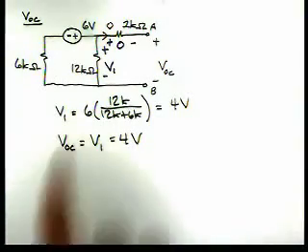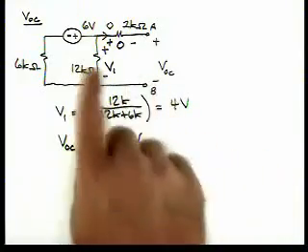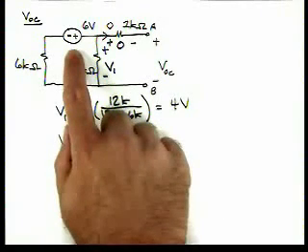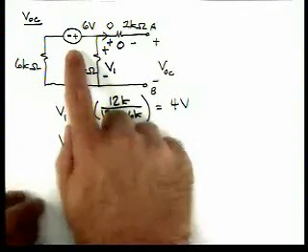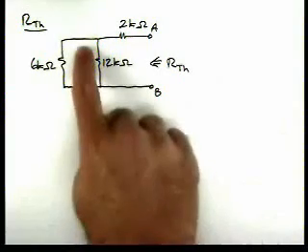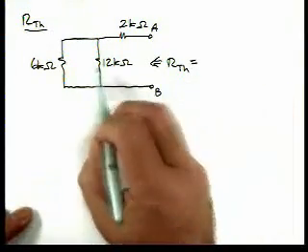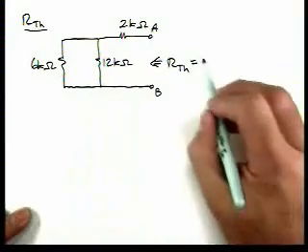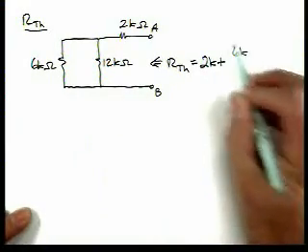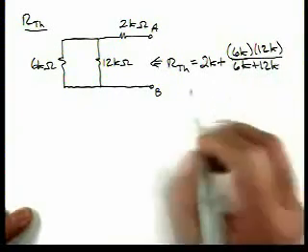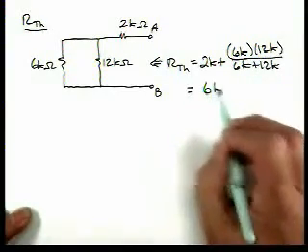Now, we need to find the Thevenin resistance, and since we have only an independent source, we'll turn it to 0. And when we do that, that becomes, in essence, a short circuit. So here is our circuit for calculating our Thevenin resistance. See, that's where the voltage source was. We turned it down to 0. So then for our Thevenin resistance, we have these two resistors in parallel in series with a 2K. So our Thevenin resistance is 6 kiloohms.